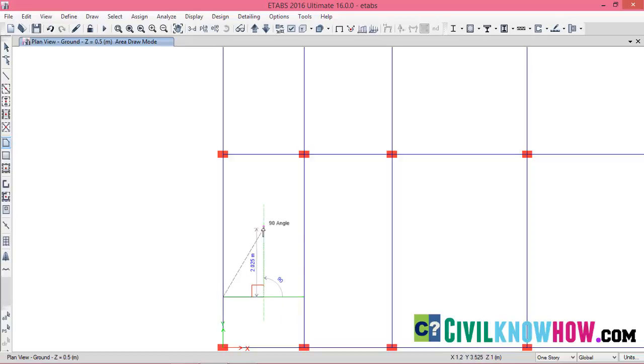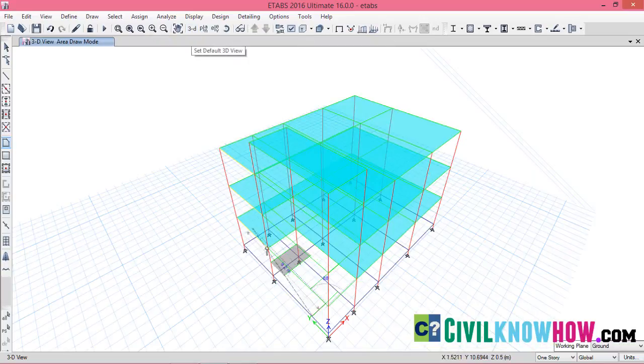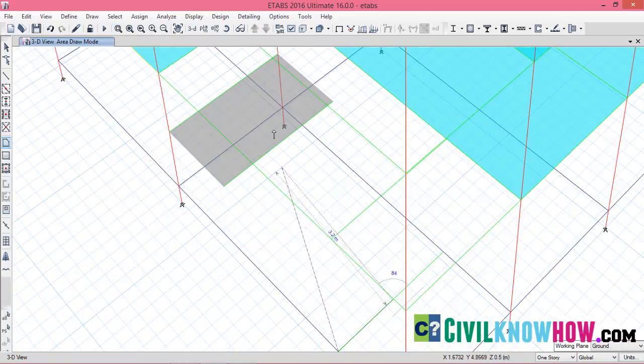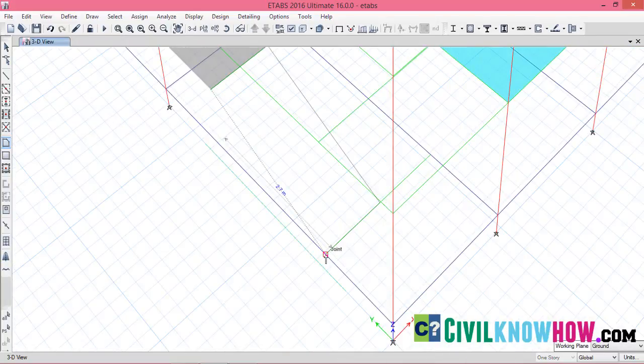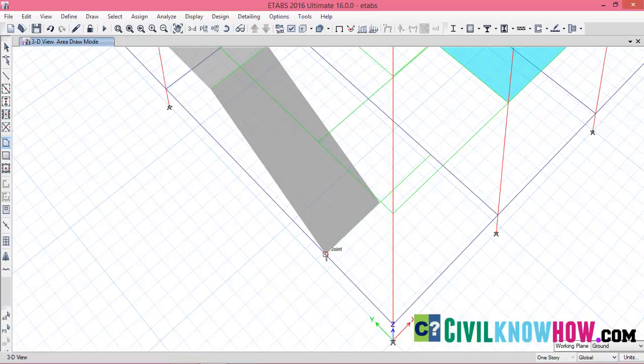and now I need to go to the middle floor. So I'm going to take the 3D view. This is quite a bit messy, but still it's a good option, and join over here in this middle point and connect it to the other adjacent point, and then come back to the ground floor. So your first stair flight is ready right now, and the next what we have to do is connect the mid landing to the first floor.